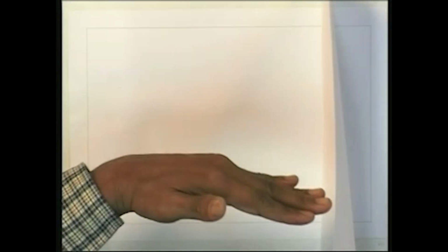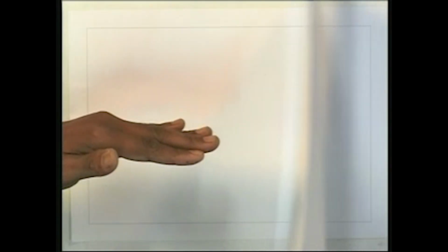So, here you can see the plate which we considered with respect to the jet. Now the jet is coming and the plate is fixed, so we have found the force. But if the plate is moving, so when the jet is acting, simultaneously the plate is also moving, that is the case of the moving control volume. So, the cases which we have considered so far are fixed control volume, but in some cases, like we have seen when the wheel is rotating, or when the plate is moving with respect to the jet action, the case is of moving control volume.